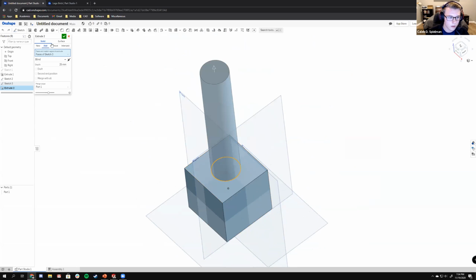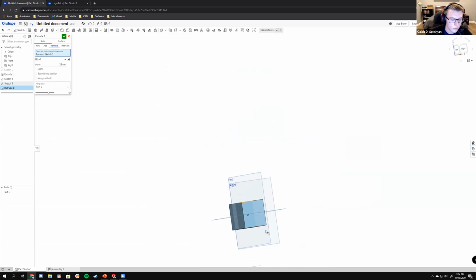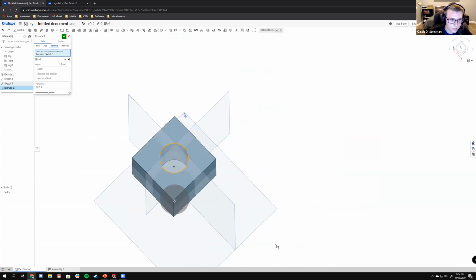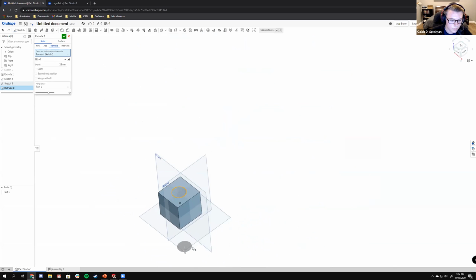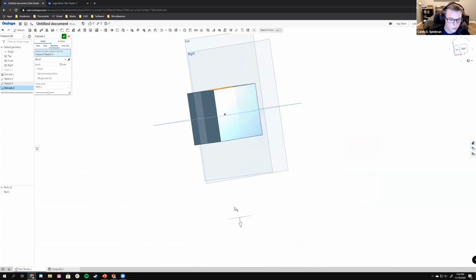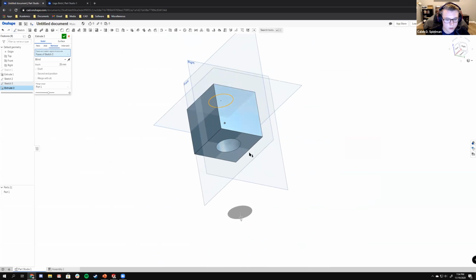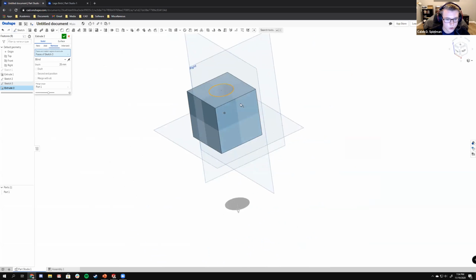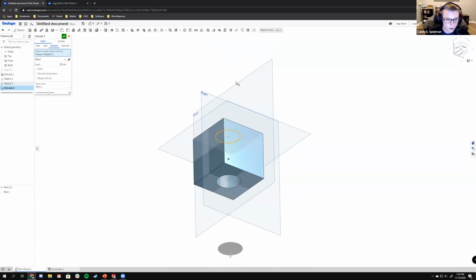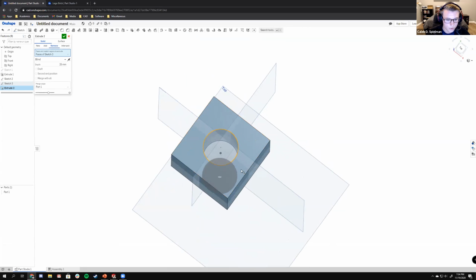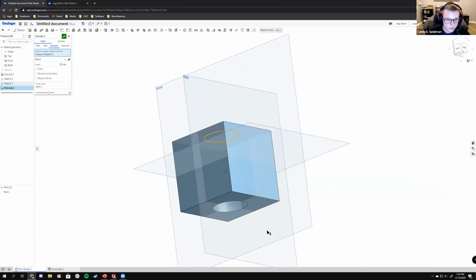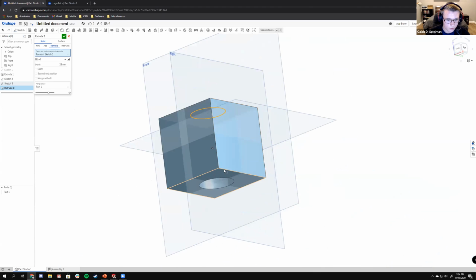Okay. So now we'll click the extrude feature again, but this time we're going to click remove instead of new or add. So we're going to remove volume. Here you can see this extrude extends far beyond what we want it to. Let's say we have a part down here that we don't want this hole to touch. Let's say we're putting a bolt that is tangent to this face, but it does not go through this face.